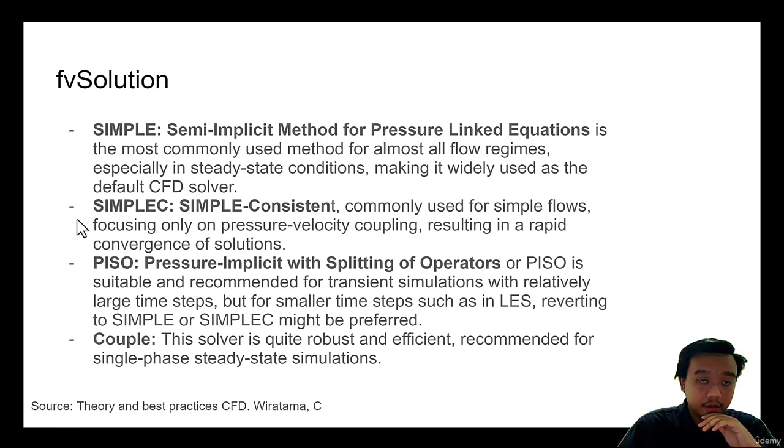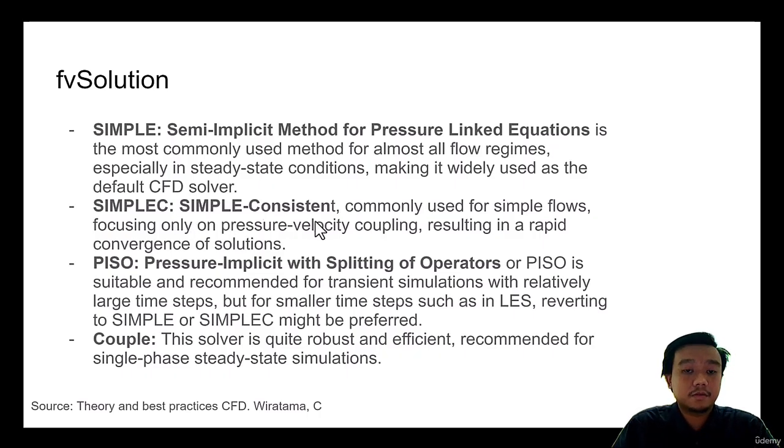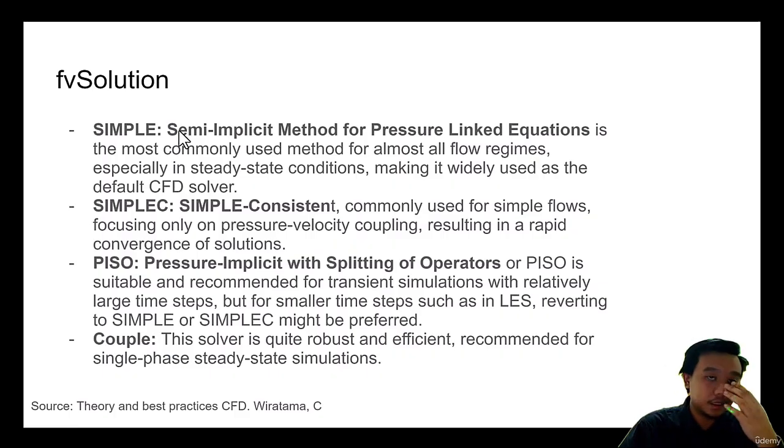And we also have other options like SIMPLEC, which is SIMPLE-Consistent, which is used for simple flow, but I don't think we will need this for OpenFOAM. And also the coupled solver, this is for steady state. But maybe the most used are SIMPLE and also PIMPLE. So sometimes in OpenFOAM templates we will find pimpleFoam, simpleFoam, and it's basically these solvers.